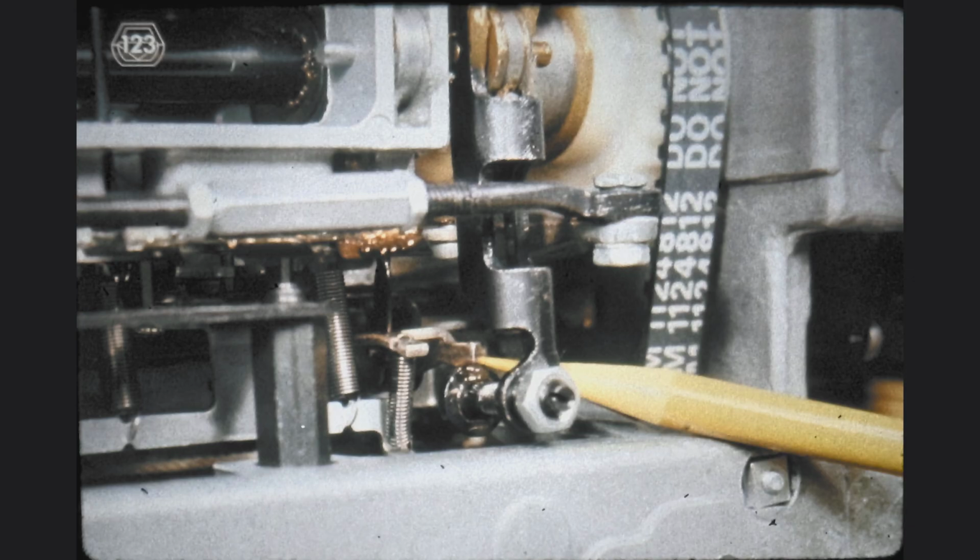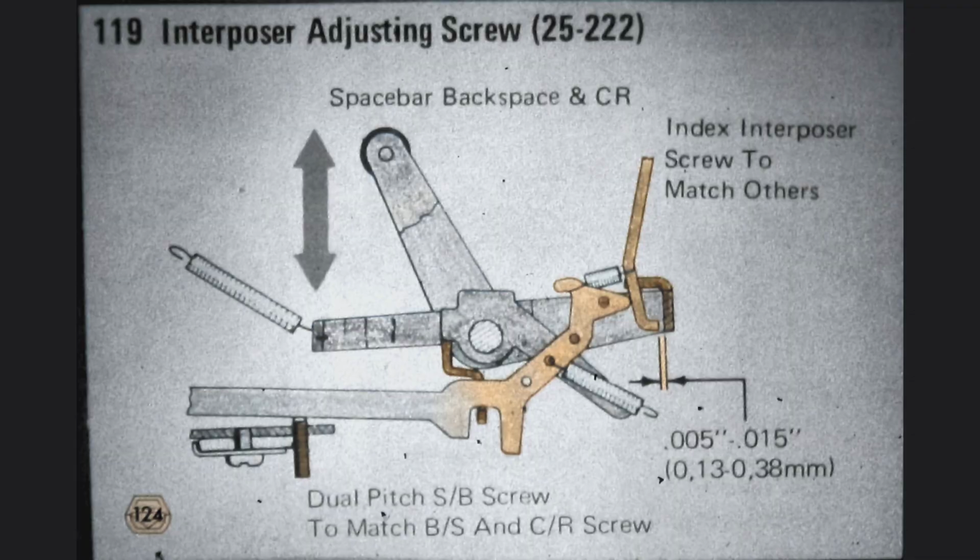If we wanted to complete all latch adjustments having to do with character printing, we would now turn to the low-velocity selector latch. However, to continue proceeding from left to right in the machine, we shall leave the low-velocity selector latch adjustment for later. The operational latches should be positioned horizontally so that, at rest, they clear the bail of the cam follower by approximately 1/4 of 1 millimeter, as shown.